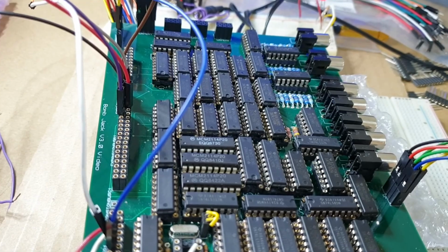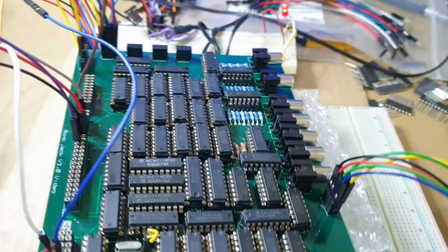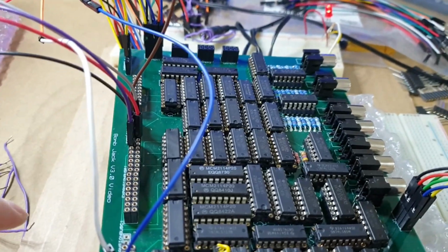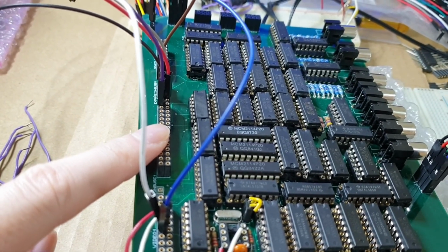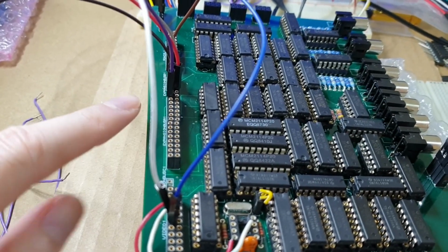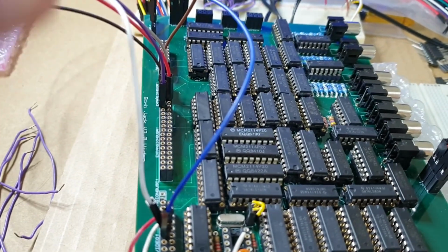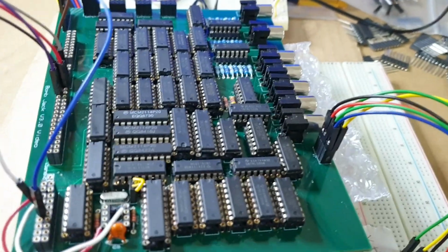I think it's going to put quite a lot of strain on here, and it restricts the configuration of how the boards can be put together. So I think in the next revision it's going to be better to change these to be right-angled IDC connectors, and then I can just have a ribbon cable going down for the bus. I think that's going to be a much better arrangement.